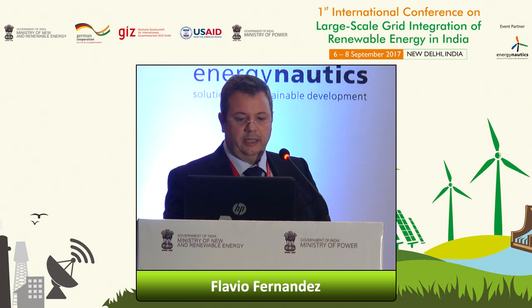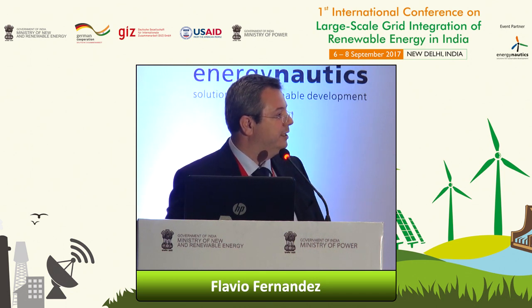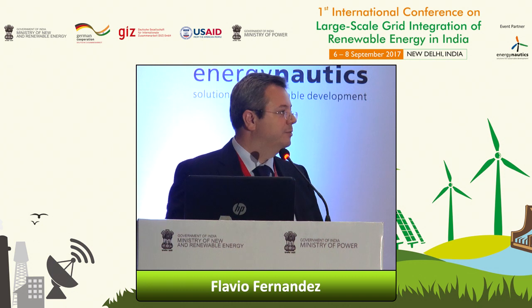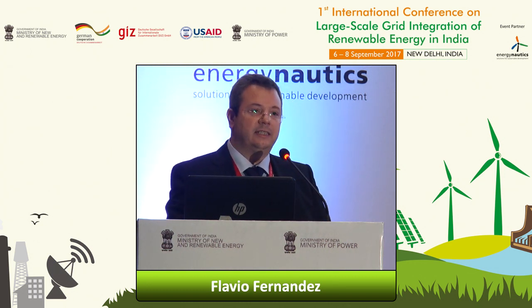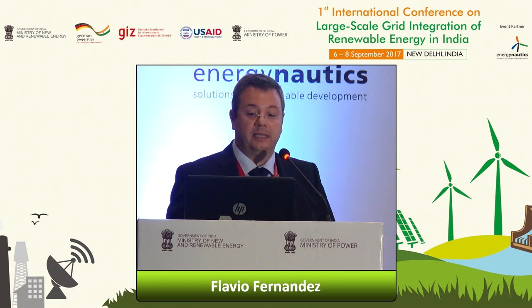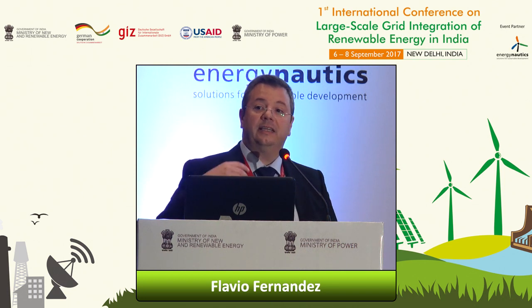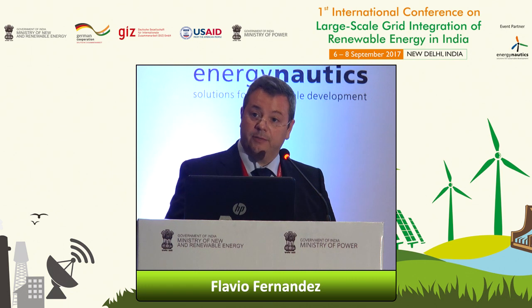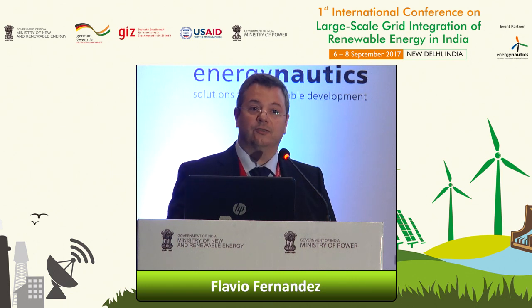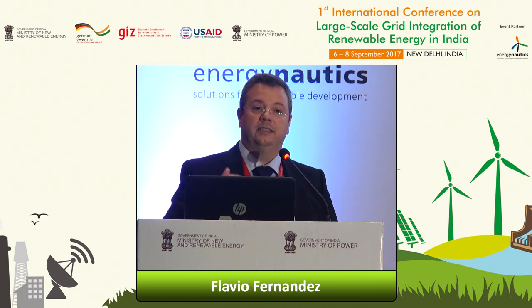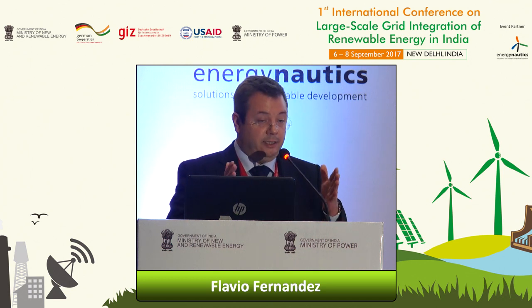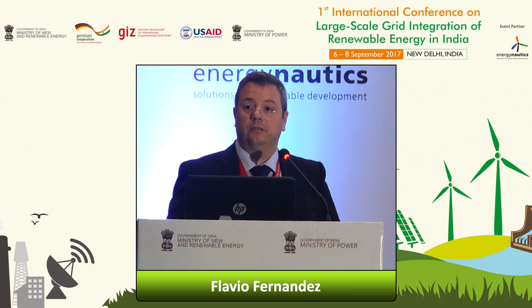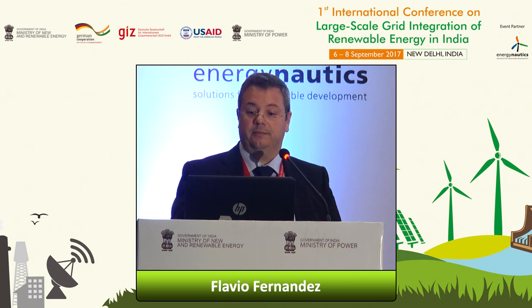You see in red the measured curve, and the blue one is the simulated one. You see that there are always differences. For example, if you look at the EMT model, you will have a better replication because you can consider saturation effects that you do not have in the RMS model. But depending on the constraints put on the model, on the requirements, the model can be acceptable or not. So just to conclude,